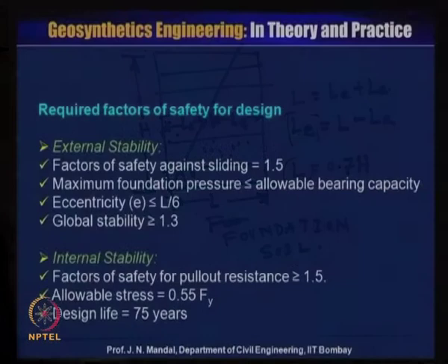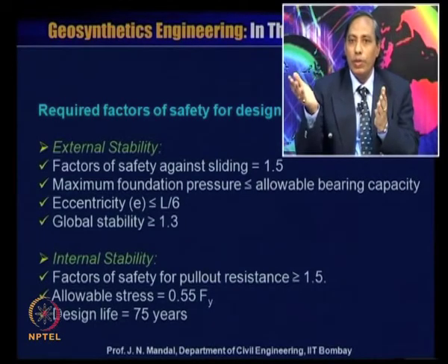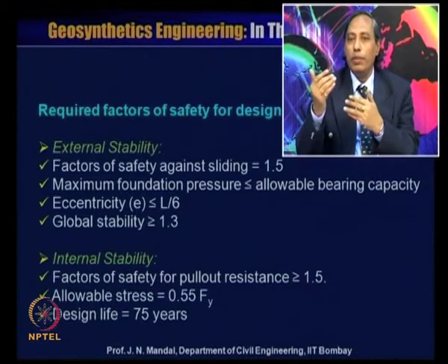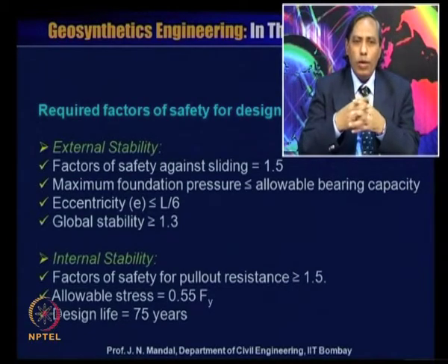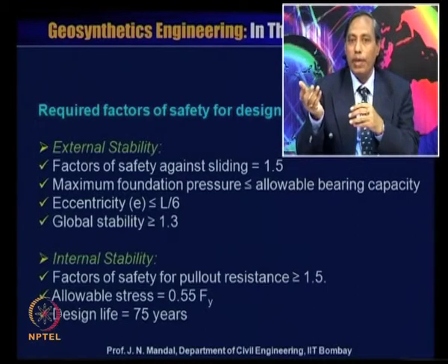Now when you design this reinforced soil wall, you require some factors of safety. You require them for the design for external stability and for internal stability. So you have to check the factor of safety against sliding, which should be 1.5. You also check the maximum foundation pressure, which should be less than or equal to the allowable bearing capacity.